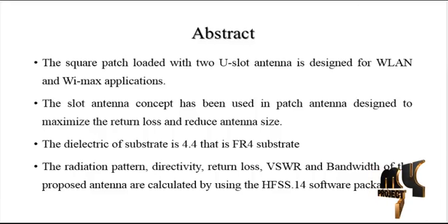The characteristic mode analysis is carried out on critical parameters such as substrate electrical thickness, slot width, probe radius and feed location variations, to assess their dominant influence on the characteristics of the U-slot microstrip patch antenna.